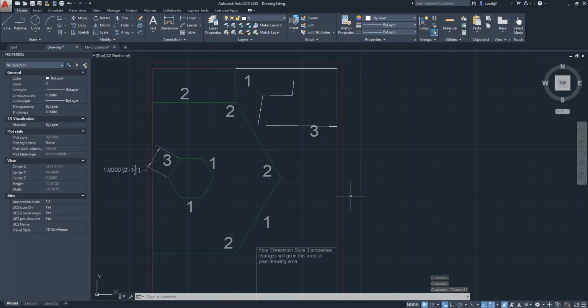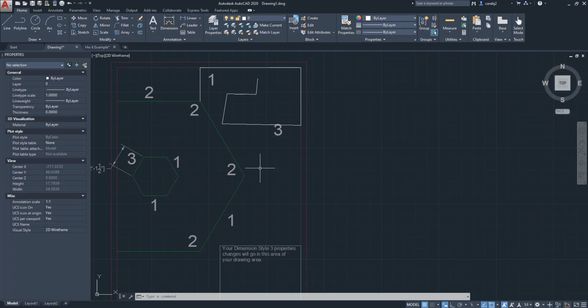It's useful more for floor plans, engineering drawings, when they're doing site plans, mechanical drawings. That way you can have multiple XREFs layered on top of each other, and that way it doesn't get confusing. So you can have an XREF for mechanical drawings, you can have XREFs for your plumbing drawings. That way they're each on their own different layer, and it just keeps your drawing more clean and organized.